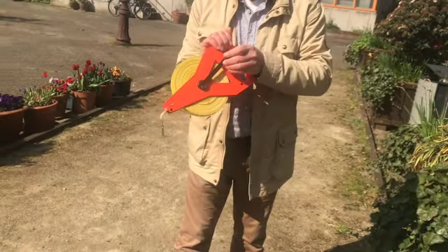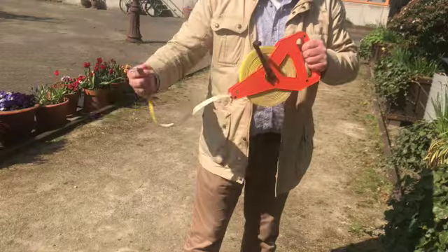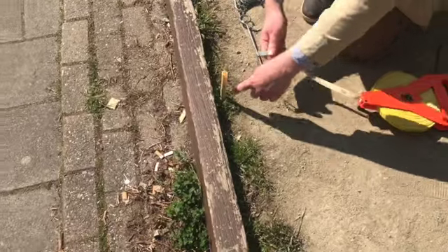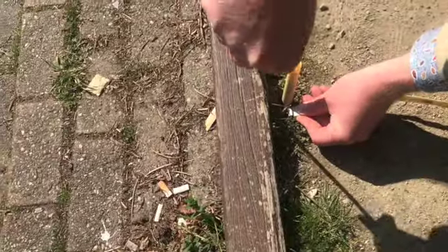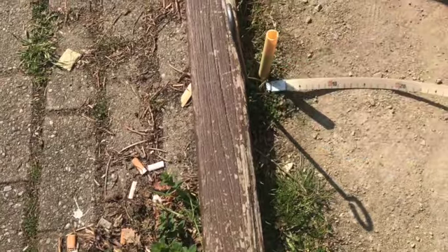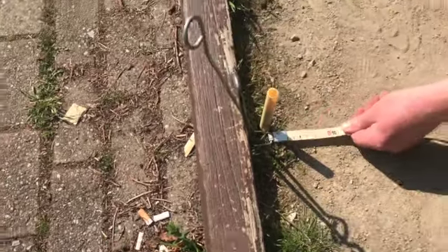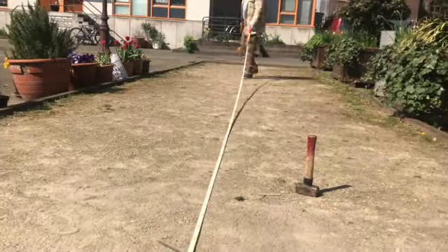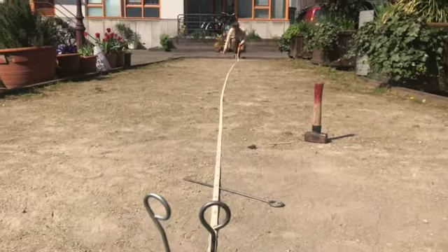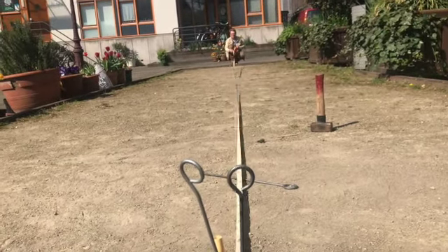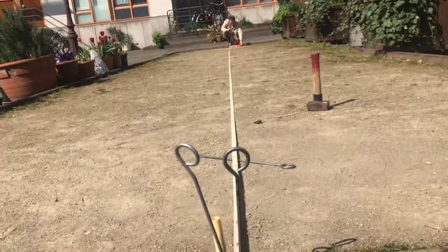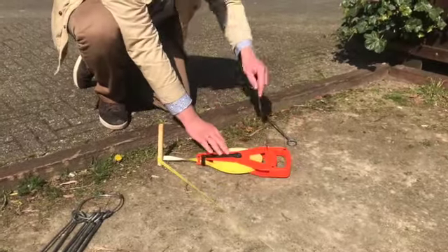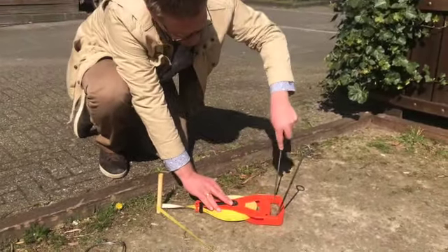Unlock the tape. To secure the 0 end, firmly use 1 or 2 arrows. Make sure the 0 end starts halfway the grid point. Walk to the opposite grid point and make sure the tape lies in a straight line. Sometimes you have to pull hard, so tightly securing the 0 end is important. Lock the tape at a convenient measure and wind it around the grid point. Place the tape on the surface and keep it under tension by securing it with 1 or 2 arrows.